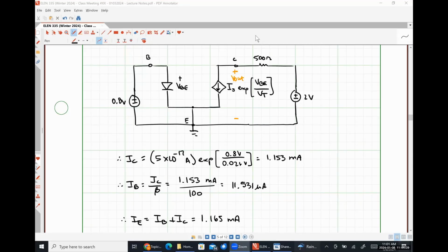So the question was, can you use the small signal diode model on a large signal problem? That's an interesting question in as much as the purpose of the small signal model is to linearize the nonlinear characteristics of the diode, right? So the large signal diode model, particularly the exponential diode model, is a nonlinear relationship between current and voltage.